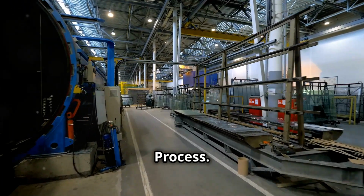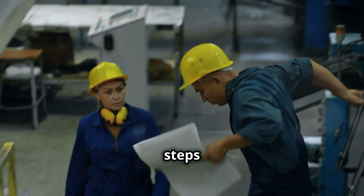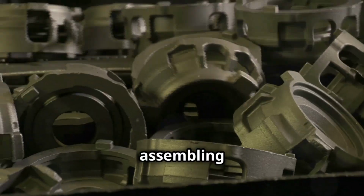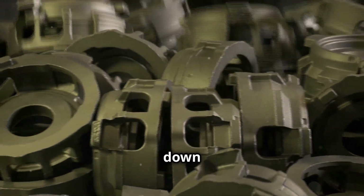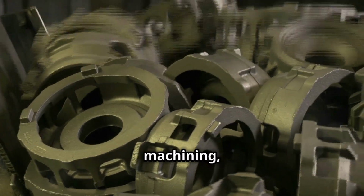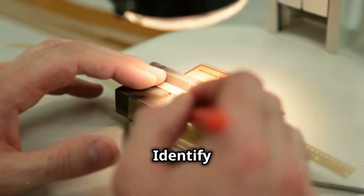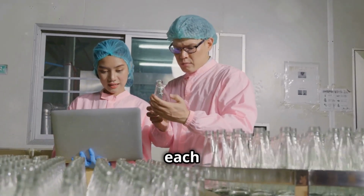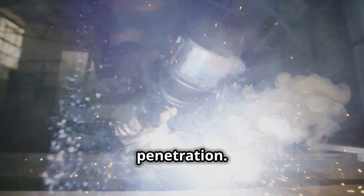PFMEA process. Step 1. Define the process. Identify the key steps in the manufacturing or assembly process. For example, the process of assembling a car engine or producing a plastic part might be broken down into stages like material handling, machining, assembly, and inspection. Step 2. Identify potential failure modes. List all possible ways each process step could fail. For example, in a welding process, a failure mode could be insufficient weld penetration.